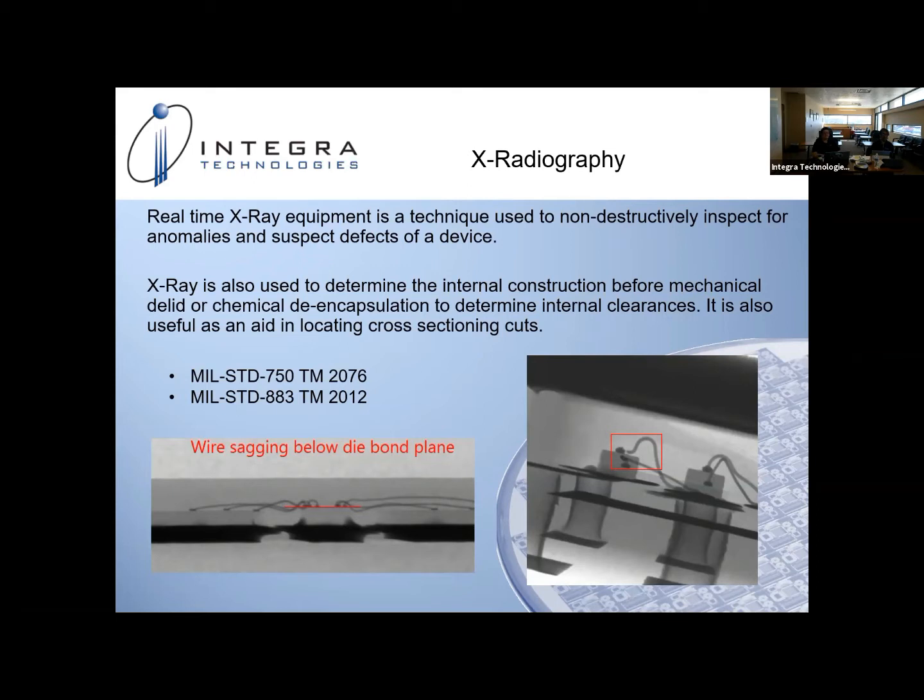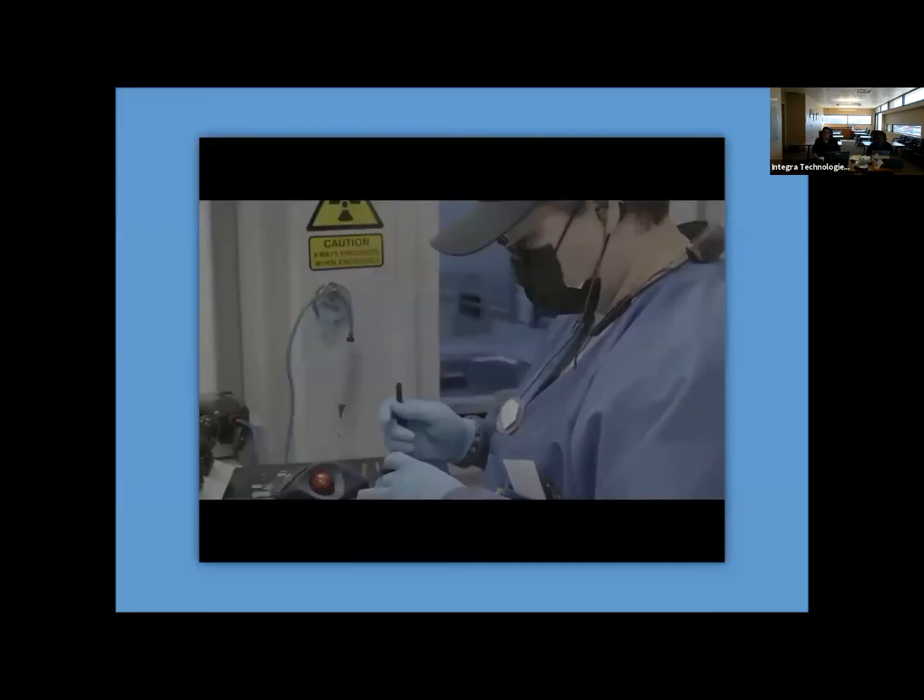DPA will tell you a lot about the manufacturing process, both from the assembly and fabrication process, and even in some cases, just fundamental design issues, especially when you're looking at the reasons why there are CTE mismatches and the likes of it. Typically also, if DPA is required, not only pre-screening DPA is done, but in a lot of cases, post-qual DPA is also done. Yeah, I think you covered it.